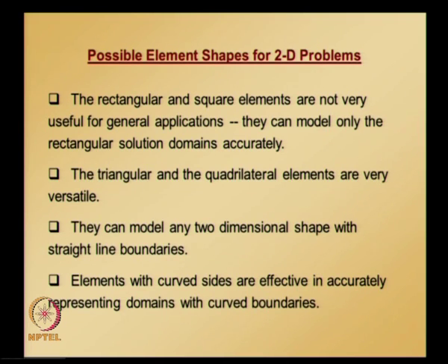So to start with, in this lecture we will derive triangular element shape functions, as the triangular element is the simplest to formulate, as it is based on linear polynomial trial solutions, which will be clearer when we actually start deriving the element shape functions for the 3 node triangular element. So the 3 node triangular element is based on linear polynomial trial solutions in 2 dimensions.